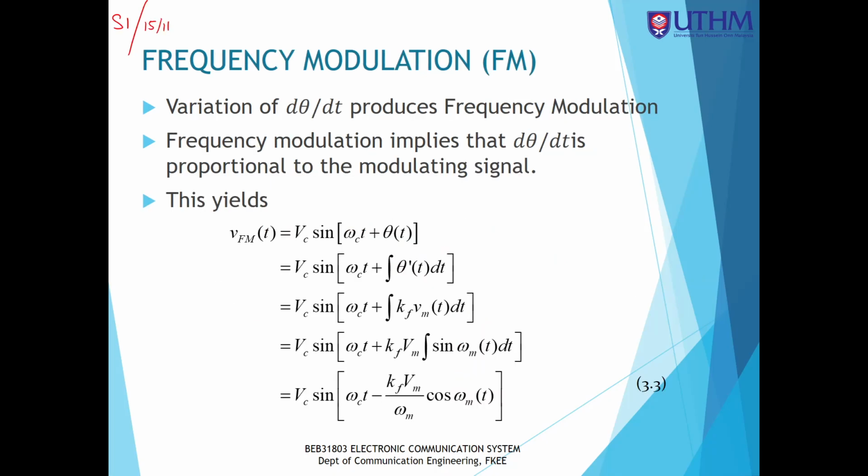For the frequency modulation, we can rewrite the equation based on the general equation of the angle modulation. So we can replace theta t with the integral of theta prime t, so we put in the values, integral of Kf Vmt.